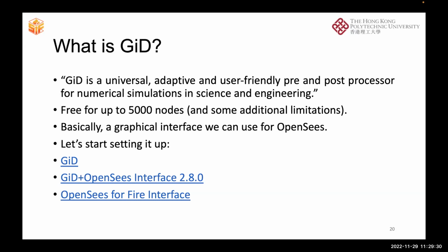It seems Liming has implemented a new mesher without telling me. Yes, we actually allow that, because when we're dealing with heat transfer issues and boundary conditions, we need a fine mesh. So we provide a function in the two codes that is a refine mesh. There is a command called refine mesh, and we define it according to the seeds for the mesh, so we can refine the mesh for the boundaries.